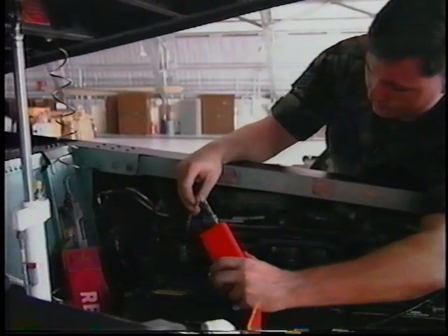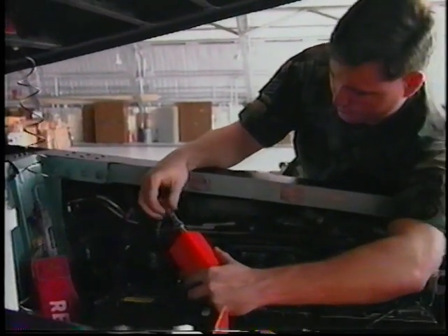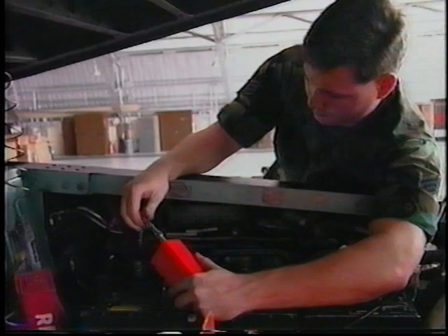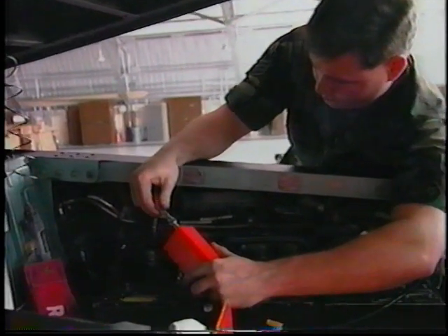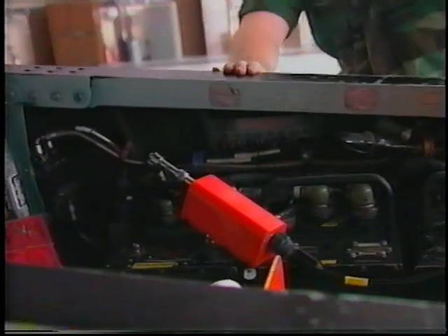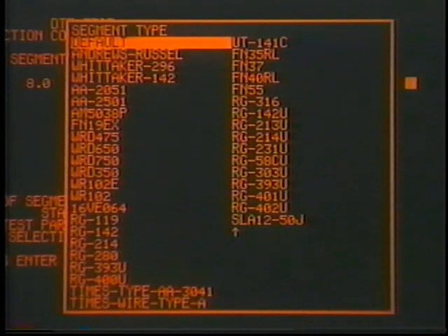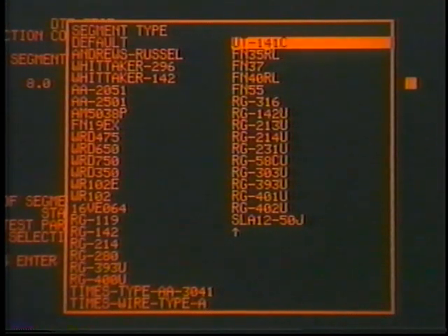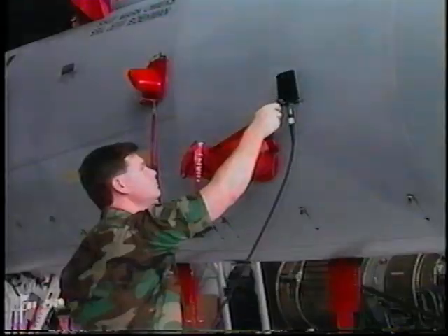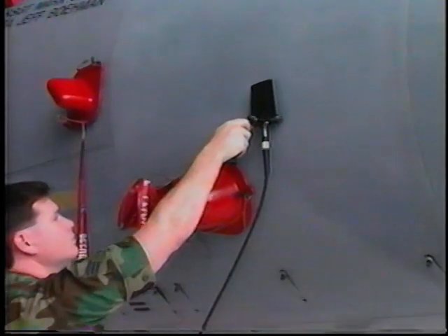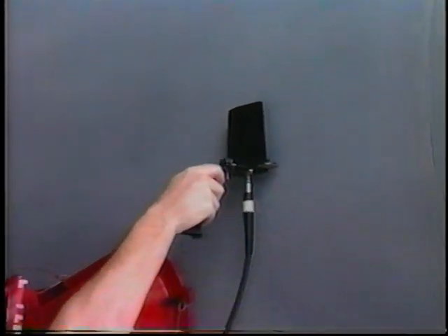It is important to know that every brand and type of cable has unique characteristics. These characteristics affect RFTLTS' ability to determine precisely where a fault may lie in the RF path. RFTLTS uses the cable characteristics as well as the correct cable length to accurately fault diagnose the RF path under test. The system operates by transmitting and receiving measured RF signals.